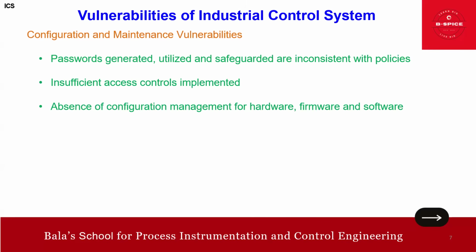To safeguard an ICS against inadequate or improper modification, for example before, during, and after system implementation, it is essential to establish a structured process for controlling changes to hardware, firmware, software, or documentation. Failing to institute these configuration change management procedures can introduce security oversights, vulnerabilities, and risk.